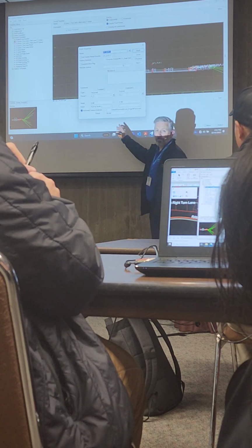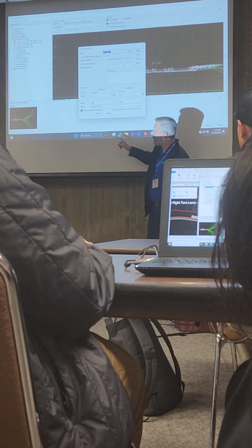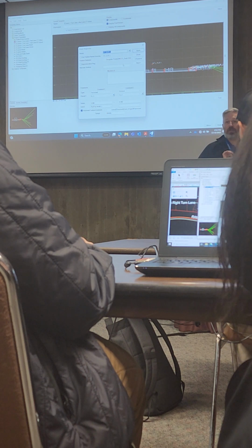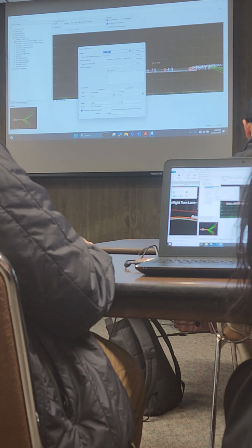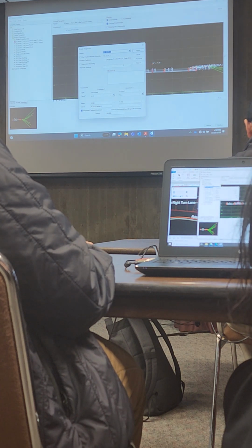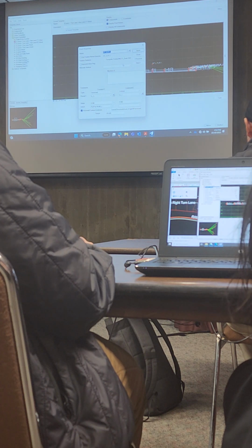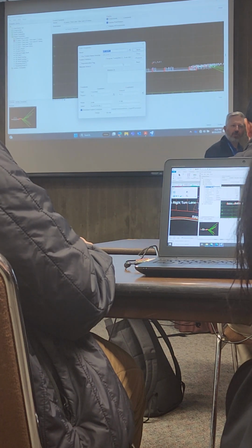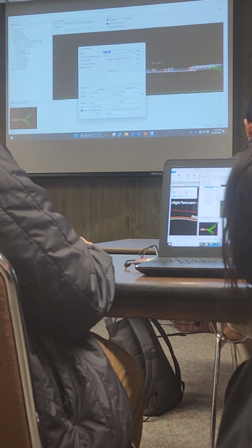Now, it's going to do it left, because it's on the left side of the road, up to 100 feet from its current origin. So wherever it is, if it's 30 feet left of the center line, from that 30 feet, it's going to go 100 more feet left, looking to see if you drew that line, no matter where you drew it and how you drew it. Straight line, transition line, going through a spiral, it's going to find it.